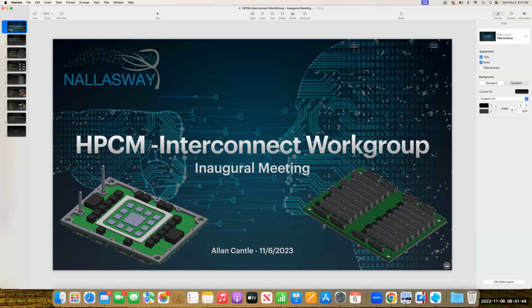So one of the proposals is we use this as a chiplet enablement platform. We use the module as an organic substrate that either the interposer substrates can go on, or you can actually put organic chiplets down as well. That's another step beyond. We're just going to use packaged parts today, and then we go beyond there.